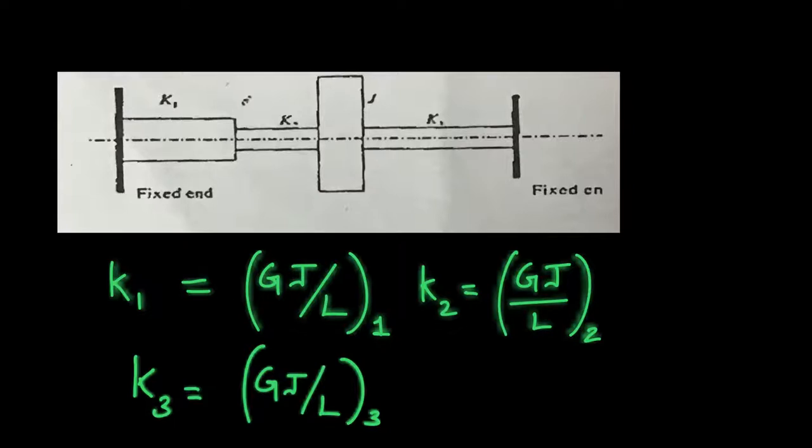So the next question is, how is this particular system going to vibrate? What kind of motion will the structure undergo when it is set into vibration? So we have three options: linear translation, rotation about a point, and general plane motion. In this case, this structure is going to vibrate in pure rotation about a given axis.